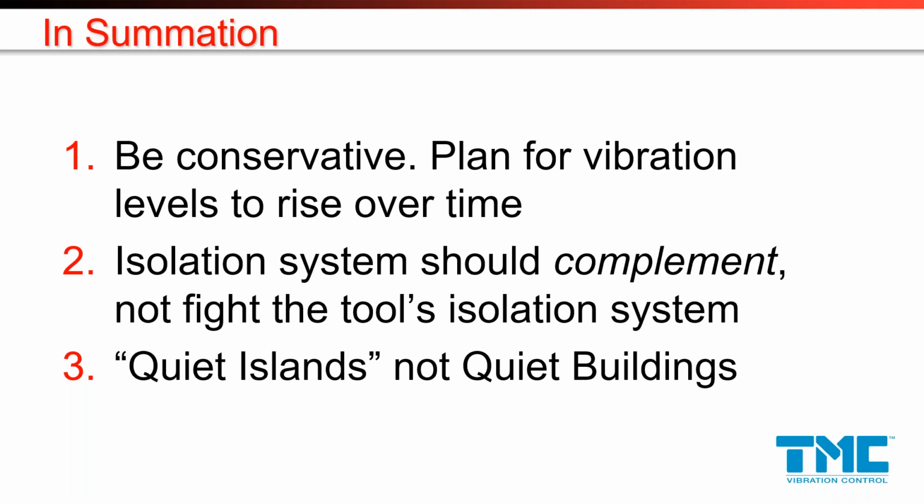In terms of the space required, the plinths tend to be not customized to the tool footprint. Plinths tend to be kind of more of a brute force approach. It's going to be larger than the footprint of the tool. They tend to be quite massive because of the length to thickness ratio you want to have for concrete, which is going to lead to a very large block. So the active systems are smaller because they are typically tailored to the footprint of the tool. They're no larger than they need to be. They're more easily manufactured to a custom requirement than pouring a large block.